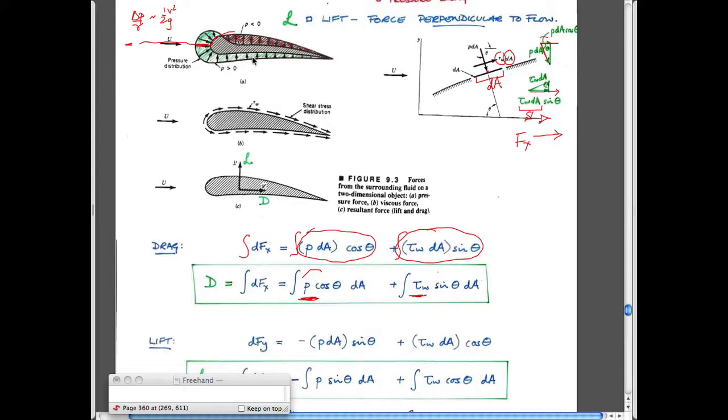And so this green stuff is the force that's acting as a positive pressure. And on the top side, the red stuff is a negative pressure relative to the ambient pressure, so this would be below the pressure here. So this would be P external. The green is P greater than P_E, and the red is P less than P_E. That's all. And of course, that's what you want on a wing, right.